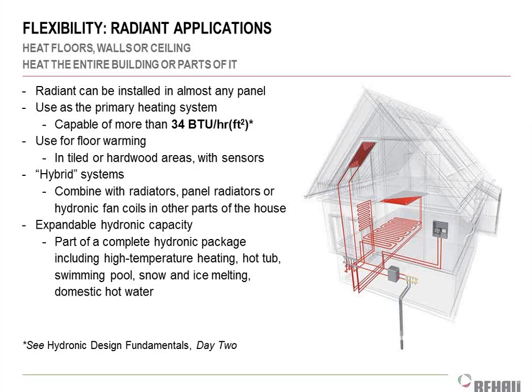Generally speaking, radiant floor systems don't do great with carpeting, and certainly not thick carpeting. The carpeting acts as an insulator. So in a normal building, right, or a normal house, thick carpeting is great. It keeps me a little bit warmer because I don't lose as much heat to my basement floor or to my slab floor, right? But with radiant, it's kind of the opposite. I want either no carpeting, right? So I want, you know, a thin layer of wood, or I want painted concrete, or I want tile, which is a great one, because those will transfer the heat up to me very nicely.